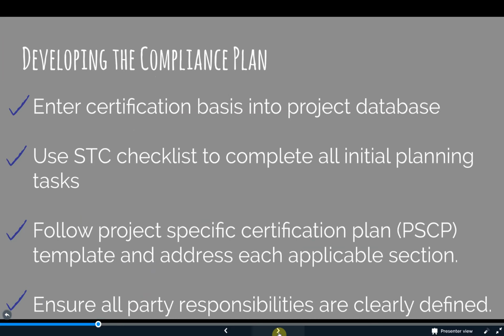As an applicant, 14 CFR 21.21 says that one is entitled to an STC once they submit all the type design, test reports, and computations necessary to show that the product to be certificated meets the applicable requirements prescribed. That's why we put such effort into developing better processes, so it's more certain that everything is accounted for.